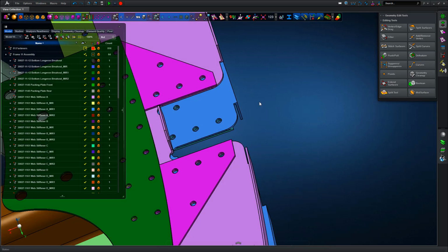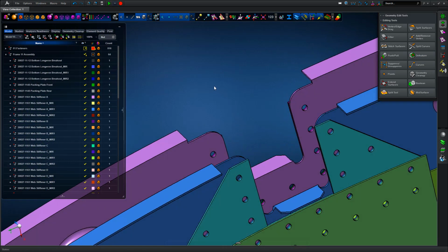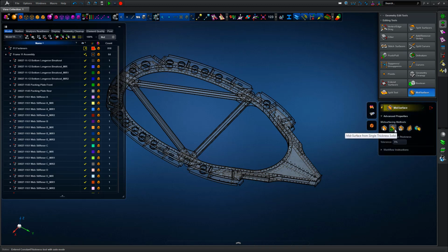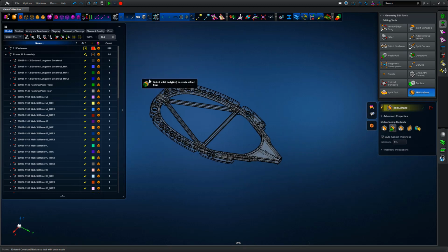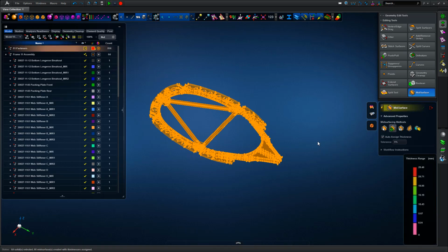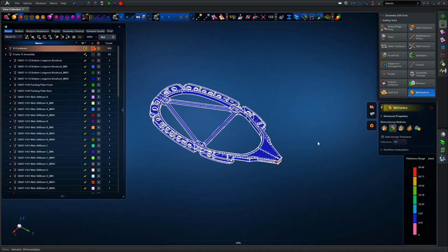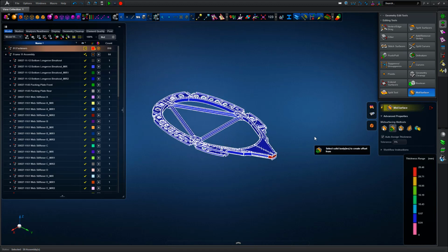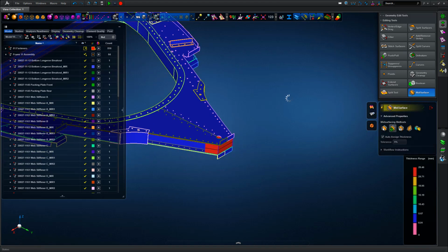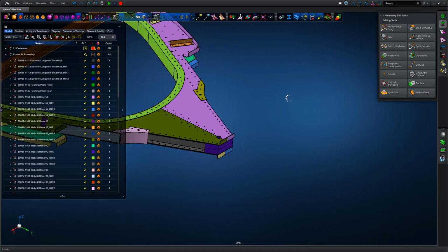So zooming in, we can see that for a couple of those regions the fillets have disappeared, and this again makes it a simpler operation in terms of our mid-surfacing, which we're about to perform. So we're going to use the mid-surface or single thickness solid with the auto assign thickness checkbox turned on. Perform the mid-surfacing operation. So Apex is creating the mid-surface and also the subsequent shell thickness property based on the original solid definition. So a very nice way of working quickly with the model, and we can see a fringe plot of the resultant thicknesses.